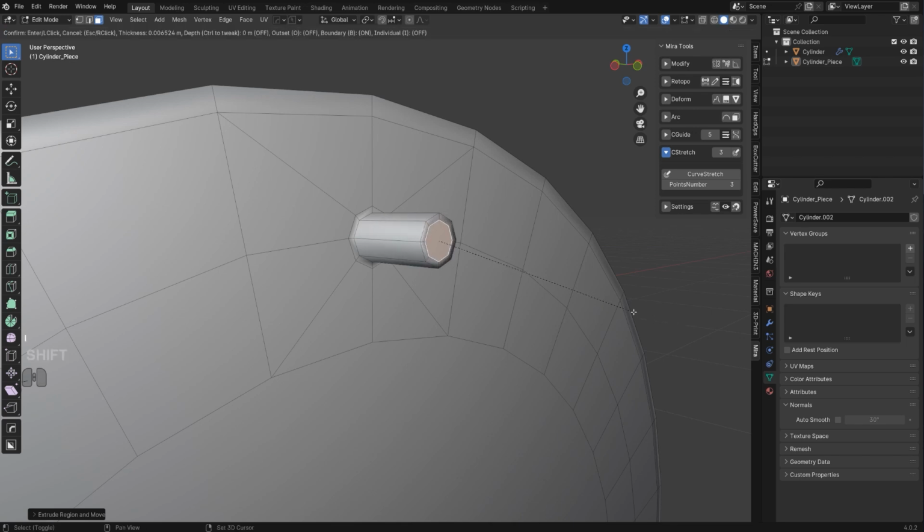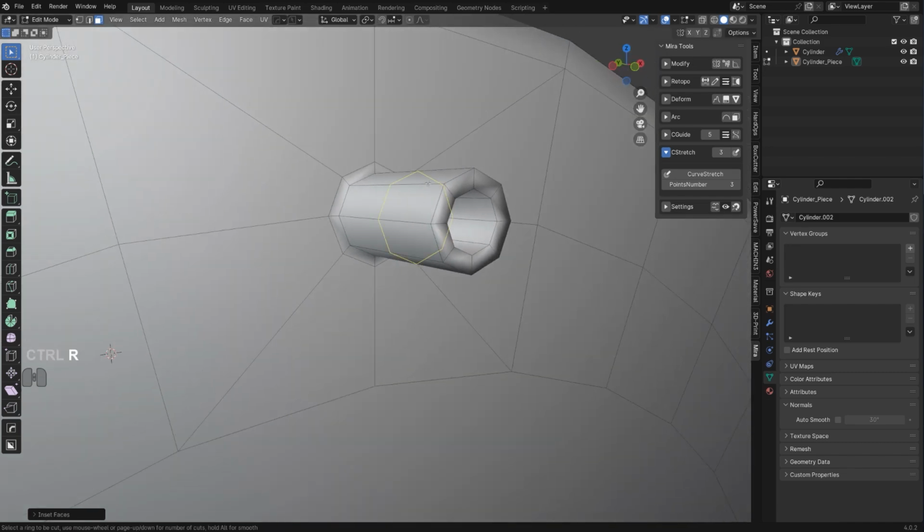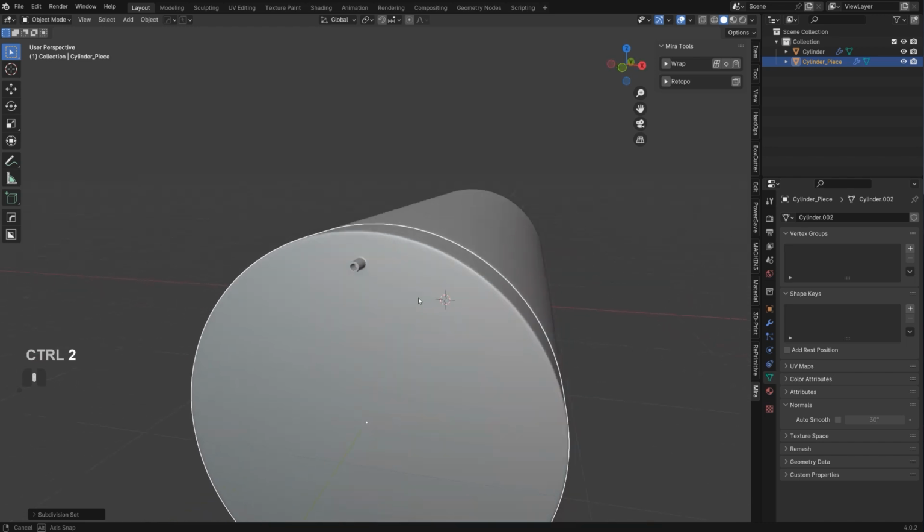And then insert it one more time, and then extrude it in, and insert it, and now we need to add some control loops. So control loops here, and scale it. We need one more control loop in the middle, and a few here, and a few outside, okay? And there we go. And this, when subdivided, should give us really, really clean results like this, all right?